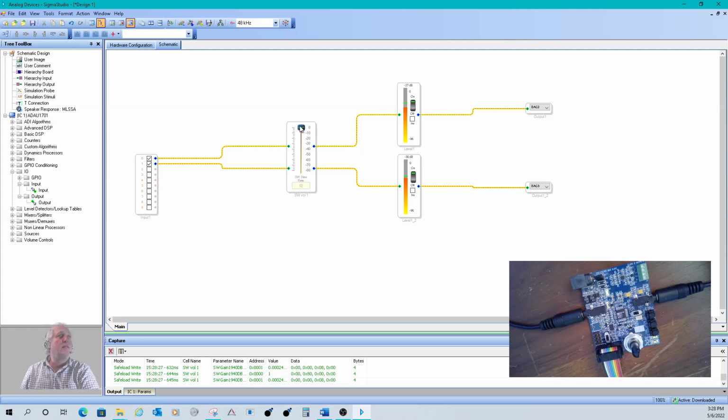And we're seeing it on the meters. There, and stop. Okay, so problem number one is I hit stop, but look, the meter's still awfully high. Is that noise? Well, no, I'm not hearing noise out of the speaker. So what it is, is the DC offset out of the ADCs. On this part, there's no high-pass filter in the ADC.